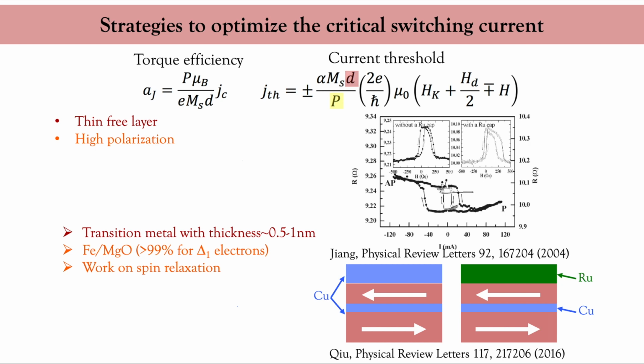If the free layer is very thin, the spin dephasing is not strong enough and the spin current that is injected from the polarizer is not entirely absorbed by the free layer. Some of the spin goes through the free layer without being absorbed, which creates an opposite torque on the outer interface of this free layer. If you add a capping layer like ruthenium, this layer acts as a strong spin scatterer that destroys the outgoing spin current, and therefore, the switching current is severely reduced.